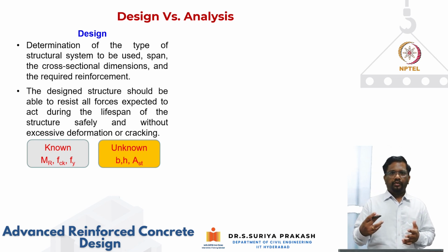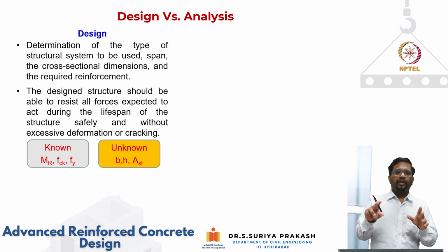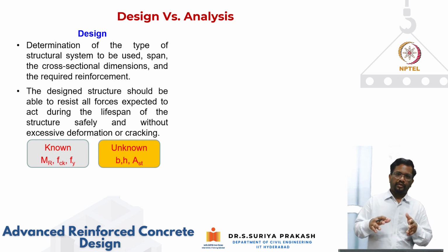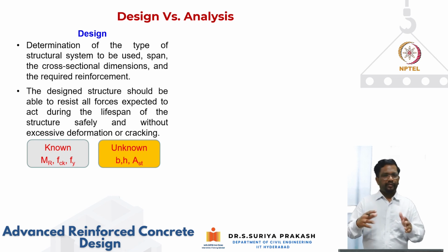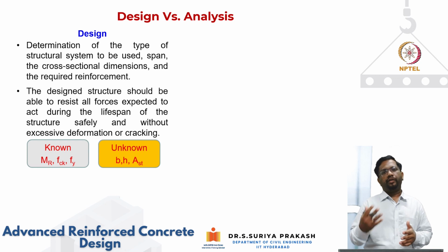Those assumptions of the sizes of the members to start the structural analysis are usually governed by some thumb rules, like what we talked about: span to depth ratio, and column dimensions can be come up with by the tributary area concept, right? Using that, to start the structural analysis, we find our internal force distribution.